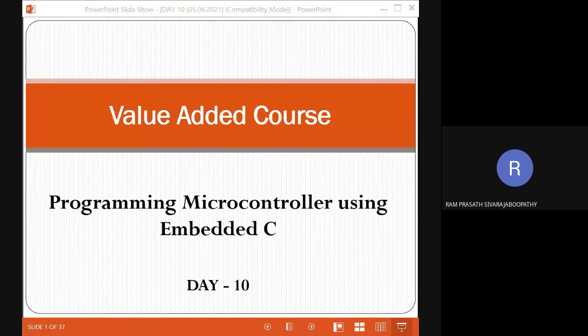Yes, okay, fine. So now my question is, if you are going for the IC MAX7219, you can interface an 8x8 dot matrix LED or an 8-digit multiplexed 7-segment display using 2 pins of your microcontroller.